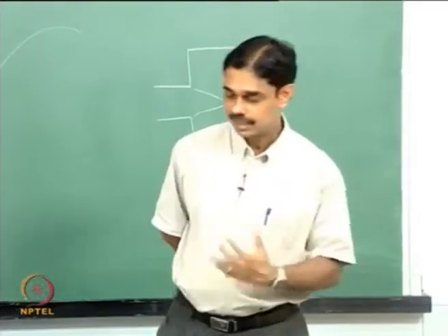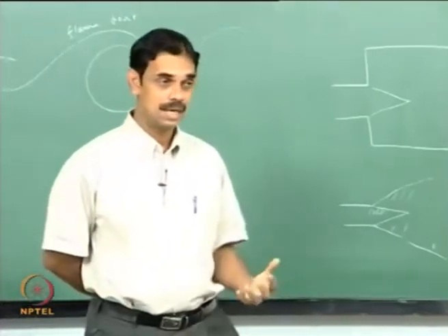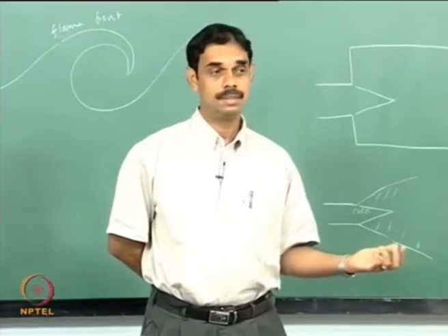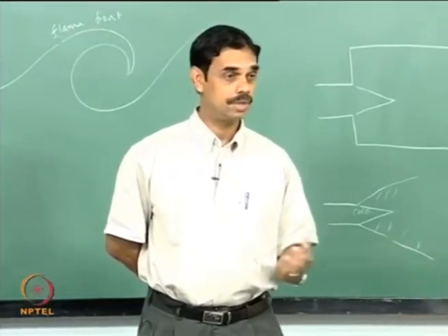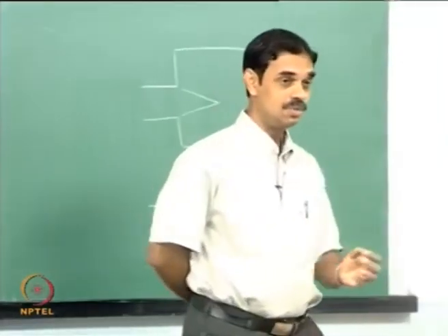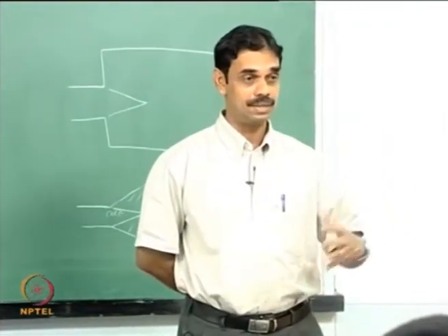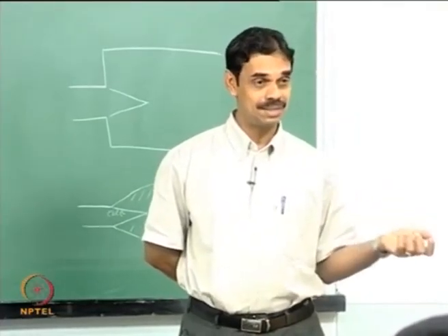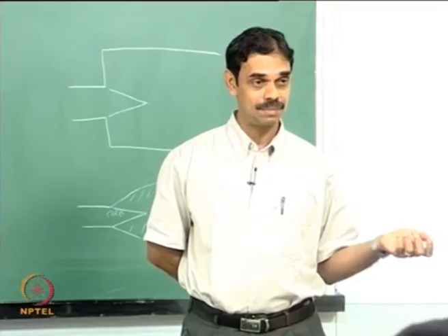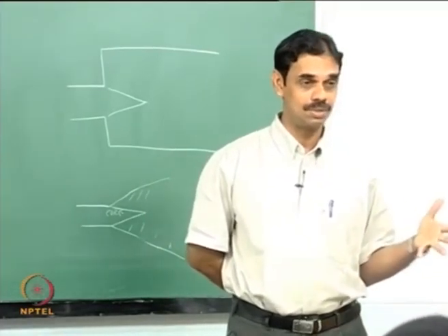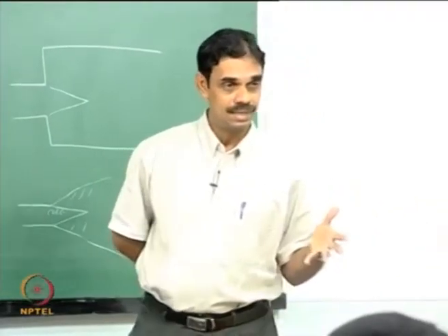Okay, you are asking whether hydrodynamic instability or coherent structures are a necessary condition for pulsating instability. No, it is not necessary at all. We showed examples, and I showed movies of a Rijke tube and also a Bunsen burner flame with a pipe around it. I didn't quite see any serious vortex related roll up, though you saw wrinkles, although you can set up those experiments to have them also, but it was not really necessary, we still had instability.